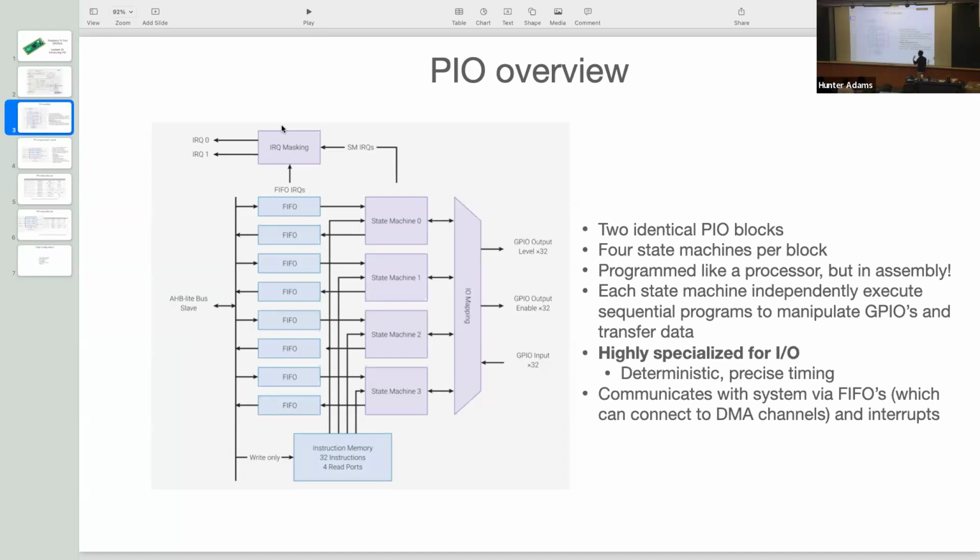The other opportunity that this presents, and if I had to speculate, I think probably the reason that Raspberry Pi would include something like this, is that when you are choosing a microcontroller for your project, you're probably basing that decision on a number of different things. Power consumption might be a concern for you. But one of the things that you're certainly looking at is the suite of peripherals that it offers. If you know, for instance, that you need to communicate with a bunch of different SPI devices, you probably want to look for microcontrollers that have SPI peripherals. Likewise for UART channels or I2C channels or whatever it may be.